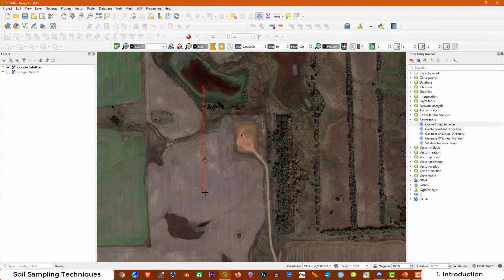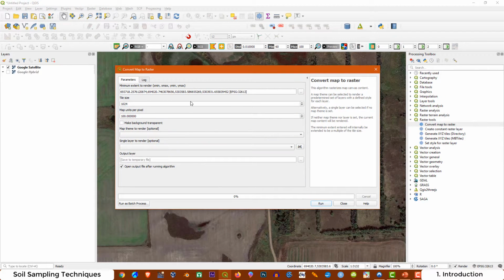It's going to be something like that, for example. The first option is good. And the second option is the resolution you want for your map. I'm going to take 0.1. If you want a better resolution, you can put a smaller number here, but this number is pretty good. It depends on the resolution of the satellite image, right? The bigger the resolution, the smaller the number you can put here.